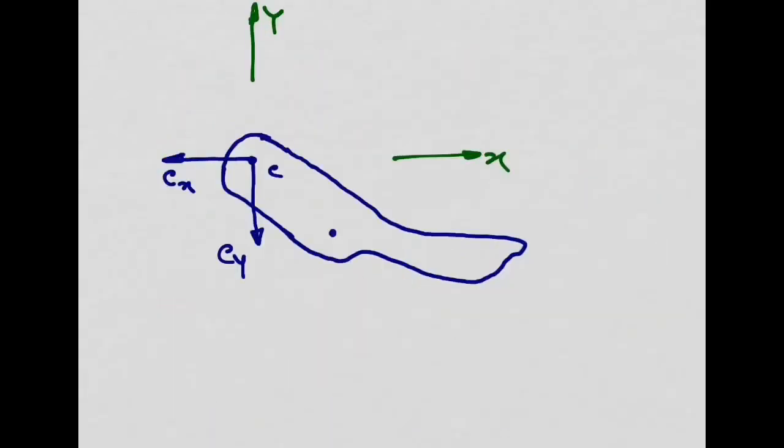So my point D is here. Do you think I need to do something like this, Dx, Dy at point D? You can do this, but you will be in trouble, and the reason is you still do not get enough equilibrium equations for your solutions.